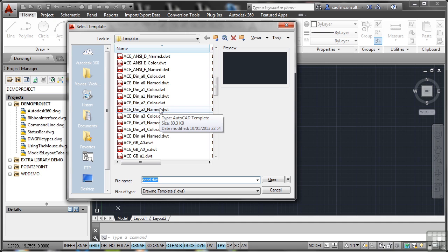Sometimes you have to look them up. Sometimes, though, you get descriptions inside the DWT file. However, in this particular dialog box, they're not displayed. So how do we get these descriptions to display? What we do is we switch on the AutoCAD startup variable.